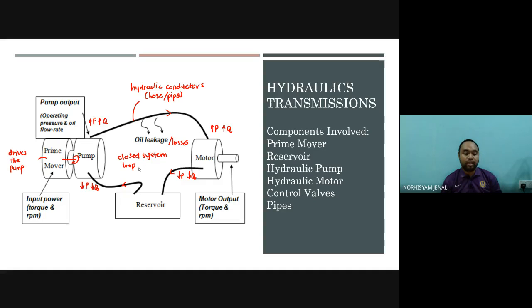That is the reason why at one point of time we always have a maintenance period. For example, after 2 years you need to change the whole liquid, because if oxidization happens in the tube, the liquid might pick up rust or whatever you have in the hose, or you might have build up in the reservoir in terms of dust or anything if you have leakage, and that will affect our system.